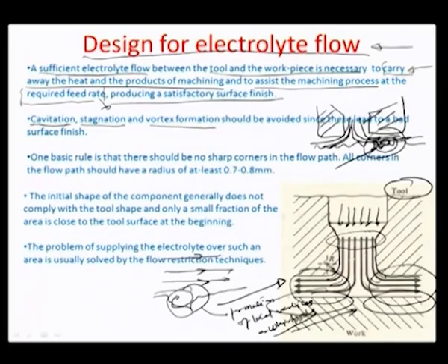Now, this can be dangerous to the ECM process, because number one, the local conductivity here is really a function of the amount of debris which is coming into this so-called local whirlpool. We can assume that the debris gets confined in this particular zone and does not get moved ahead. The remaining debris generated from, for example, this surface or the other surfaces would get carried away, but this local debris does not go ahead anymore. So, there is a change in conductivity, a change in machining rate, a change in so many parameters associated with this vortex formation.